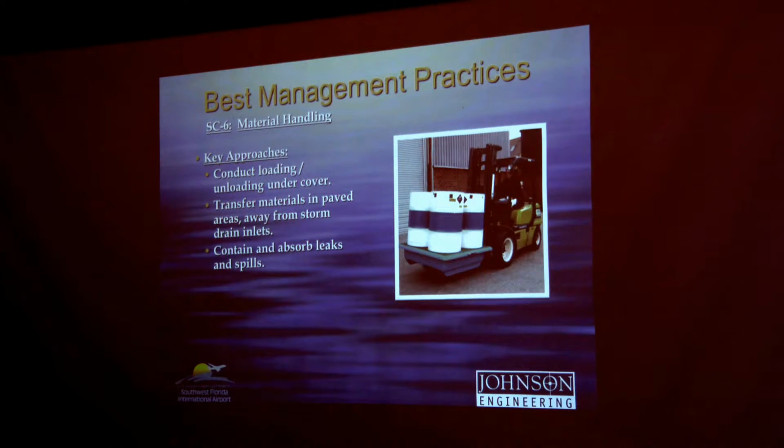SC6, material handling. Key approaches here include conducting loading and unloading activities undercover, transferring materials in paved areas away from storm drain inlets, and containing and absorbing leaks and spills as they occur. One of the big items here to pay attention to is where the storm drains are located compared to where you're conducting these material handling operations.